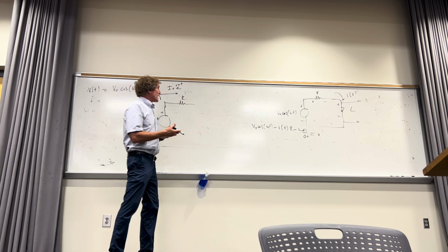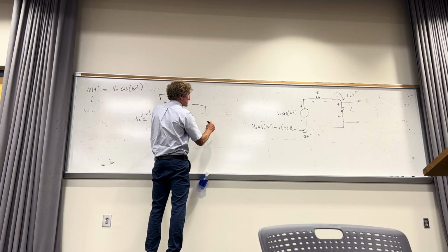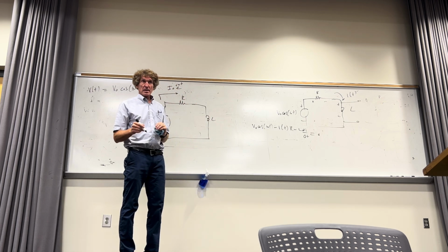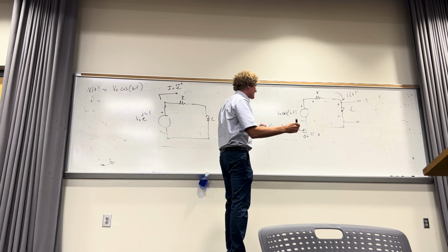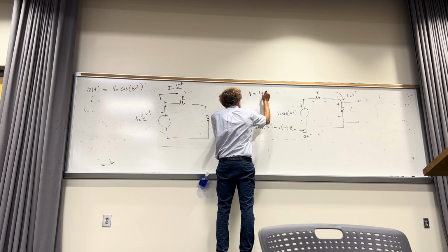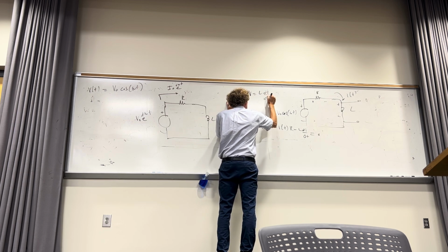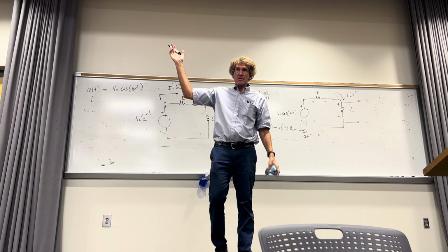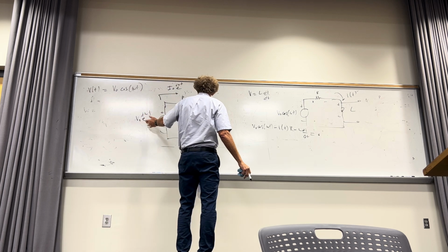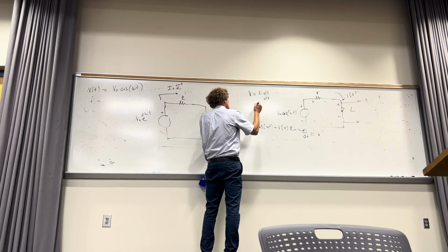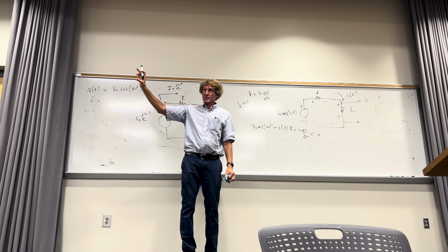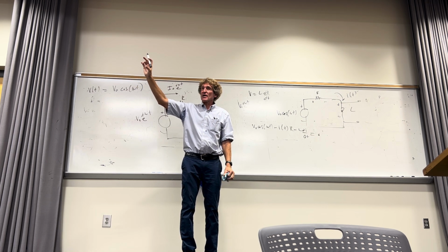You with me? Now, you come over here and you write the inductor down, and I've got an inductor here, L, right? Keep watching. Some of you probably know where I'm going with this. Remember, the voltage for an inductor is L di/dt. Do you remember me telling you that? How many do? That's in the time domain. Go ahead. We're still in the time domain here. We're not going to be there for long. I can put down over here V naught e to the j omega t. Let's say that's right across the inductor. Follow me? Just assume that voltage is across the inductor.